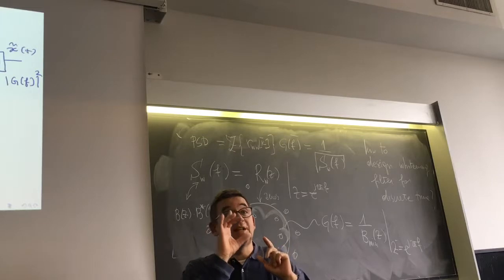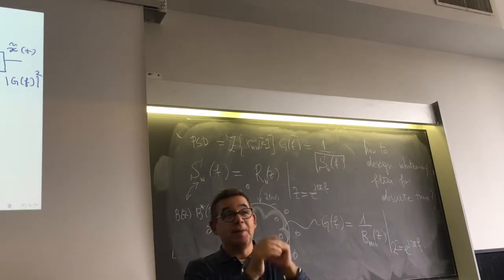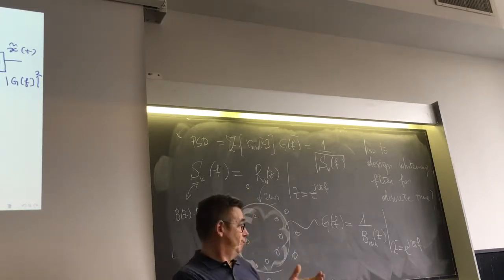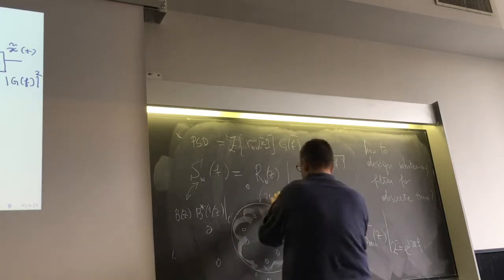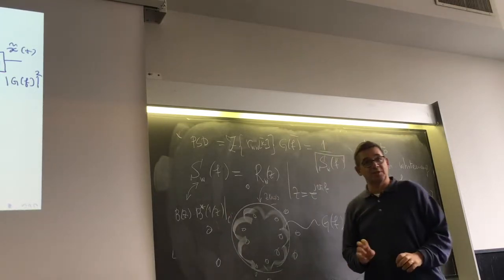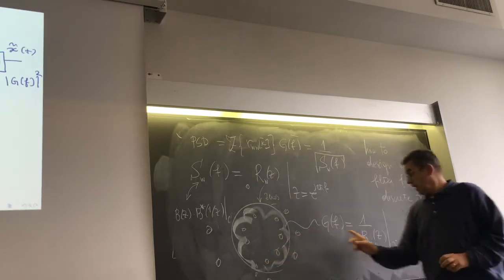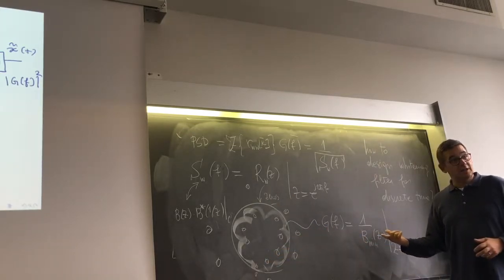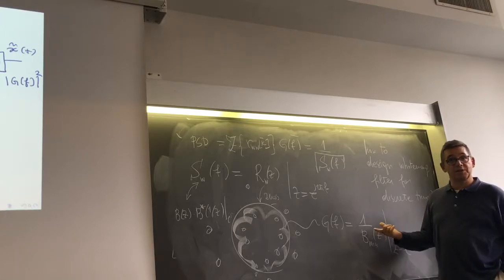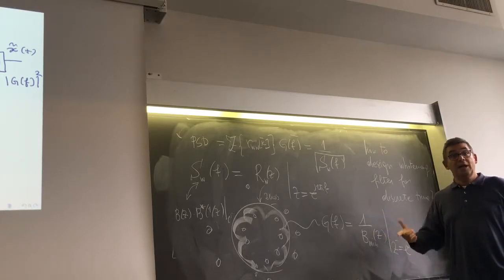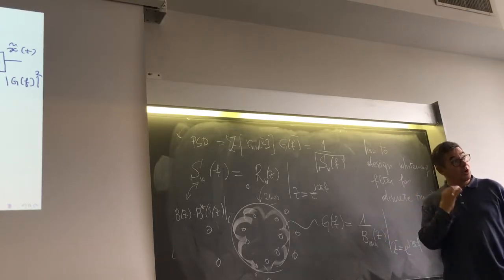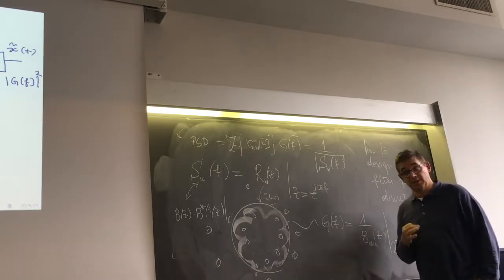If the filter that I'm looking for should be anticausal, perfect. I'm selecting all the roots, all the zeros outside. And then the zeros outside, which are the opposite around the circle of this one, correspond exactly to an anticausal filter, which is stable.